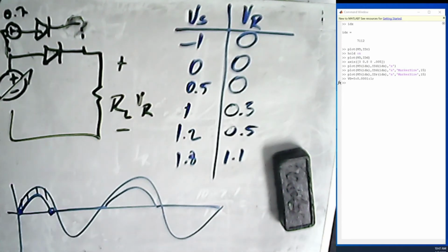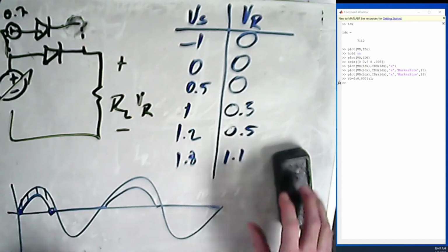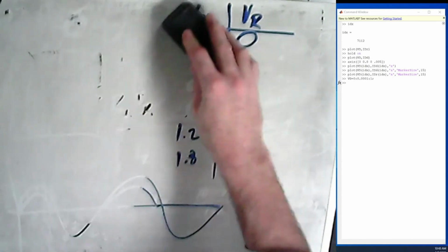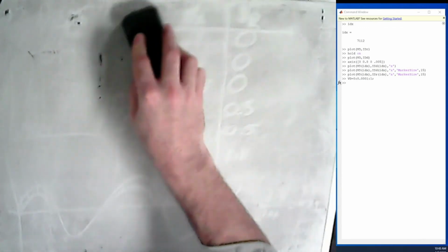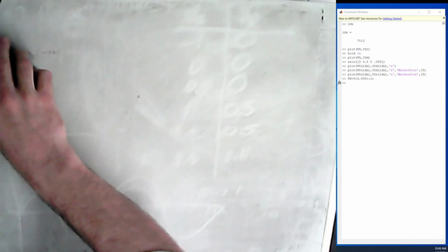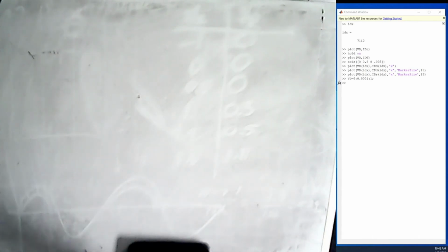This does put some limitations on our rectifiers, and that's kind of what I wanted to point out about all those rectifiers. Think about when we go back, think about how many diodes you have to go through for each of those rectifiers. And that's how much voltage drop you're going to get. And so that's lost power, that's inefficiency. Let's just do a little bit of thought on this as well.